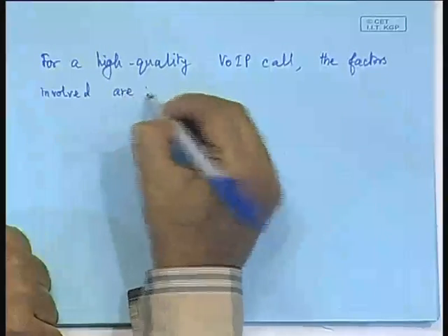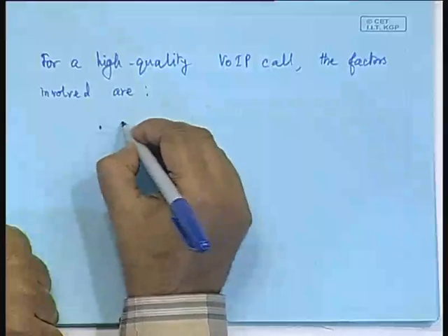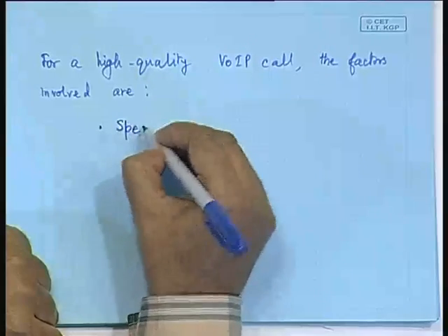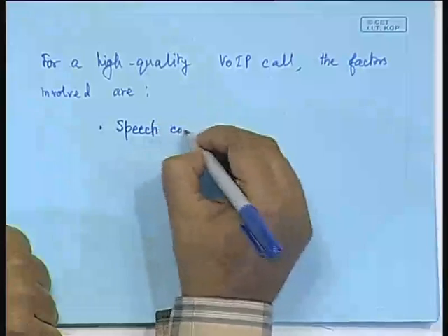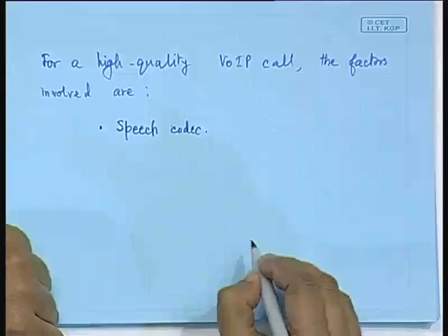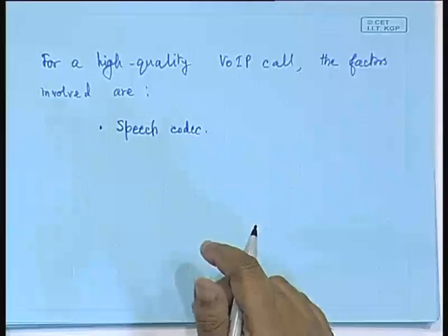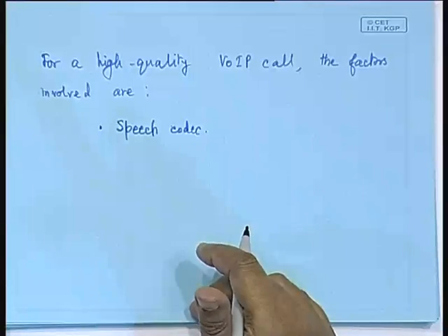First is, what quality of speech codec are you using? There is a wide variety of speech codecs. Some speech codecs are very low bandwidth speech codecs, where the compression factor will be very high.